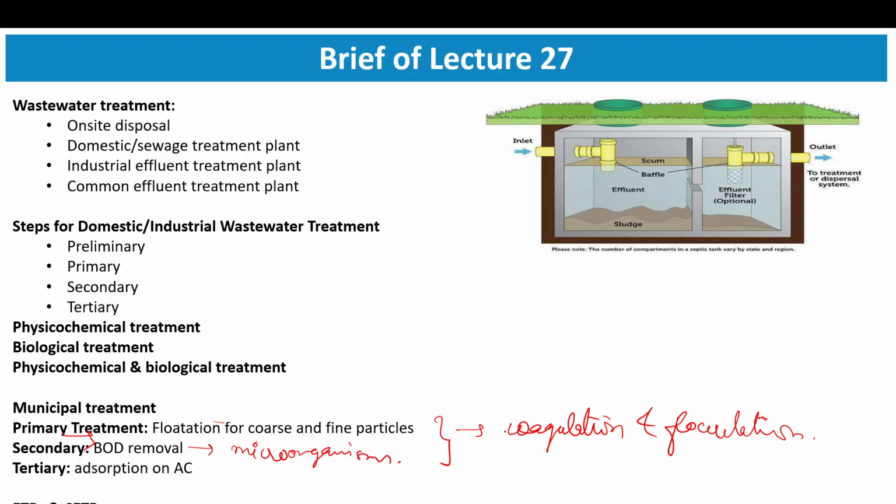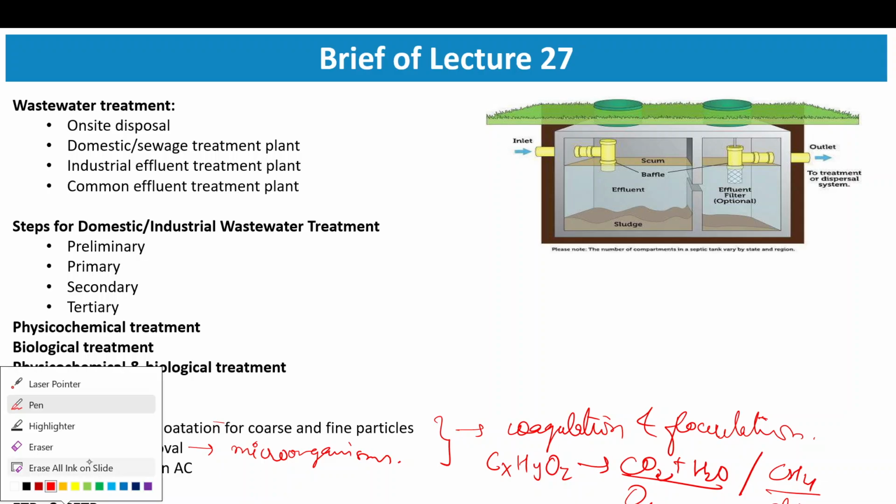What we are doing is converting BOD, which is nothing but any organic that is present, into CO2 or CH4. So in the presence or absence of oxygen, we are converting this organic into either CO2, or in the absence of oxygen, CH4.